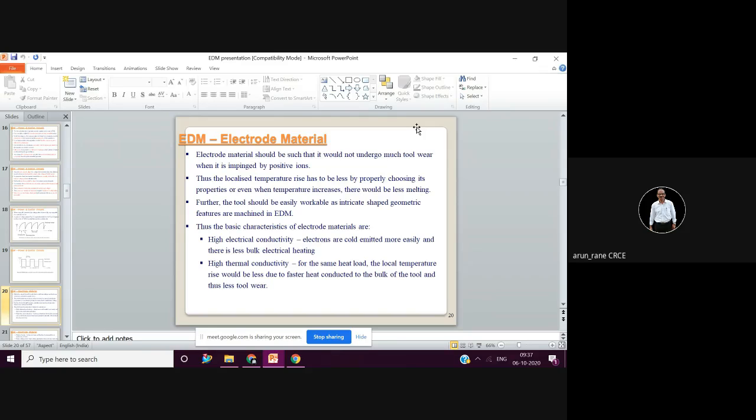Then you send it for heat treatment, in which the material gets harder. You receive it, then you use a graphite electrode to do the roughing and semi-finishing. You leave a stock of 0.1 or 0.2, that is from 1 mm to 0.2 for the finishing, and then you use the finishing electrode made out of copper. So this is how an engineer does this work.